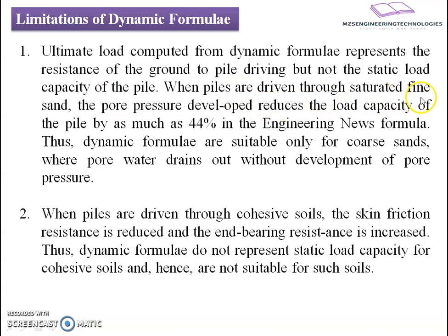When piles are driven through saturated fine sand, the pore pressure developed reduces the load capacity of the pile by as much as 44% in the Engineering News formula. Means when the soil character differs, if there is water saturated soil, then there is pore pressure which is going to act, and thereby it reduces the load carrying capacity of the pile, which was not accounted anywhere in your dynamic formulation. Thus, dynamic formulae are suitable only for coarse sands where pore water drains out without development of pore pressure. So this dynamic formulation is not valid for soils which have saturation.